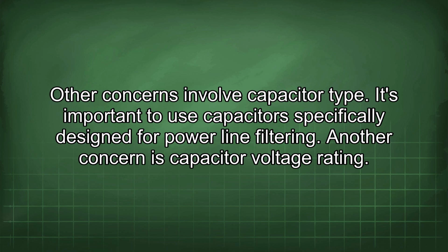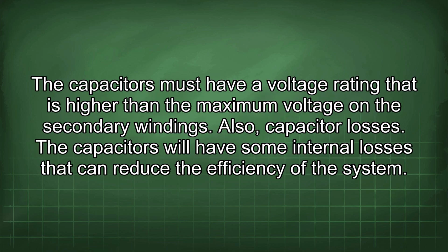Another concern is capacitor voltage rating. The capacitors must have a voltage rating that is higher than the maximum voltage on the secondary windings. Also, capacitor losses. The capacitors will have some internal losses that can reduce the efficiency of the system.